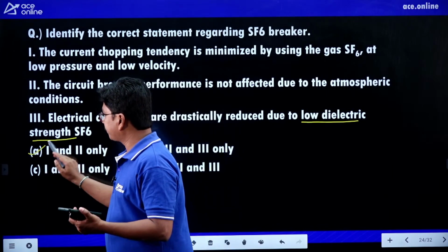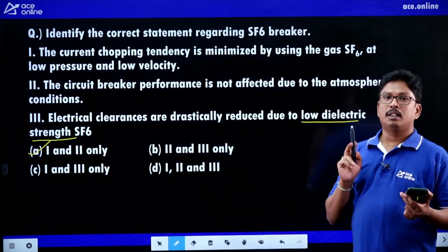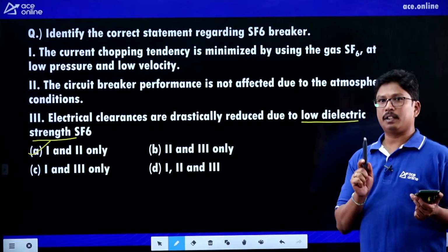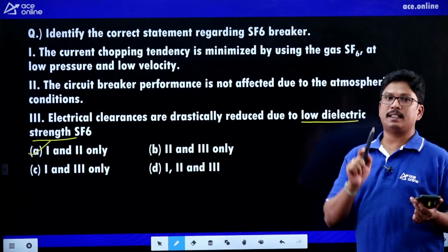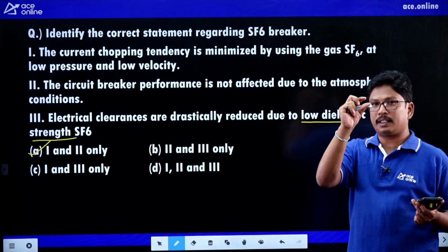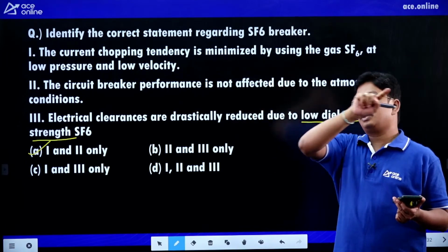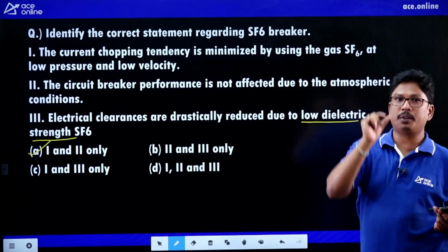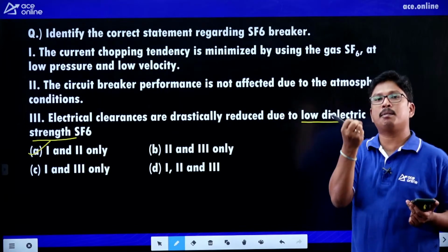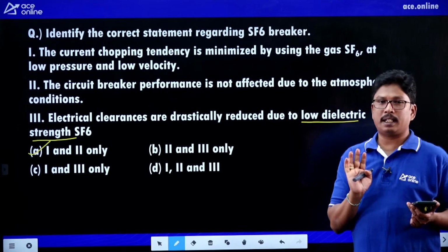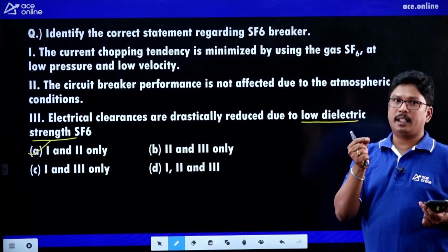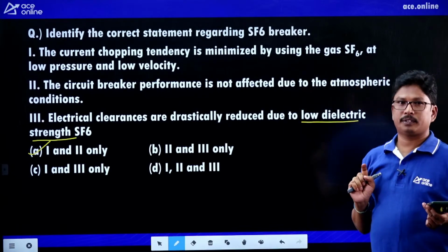Yes, Sai Kumar. Actually, the fuse element decides the fuse current rating. If the fuse conductor is somewhat thin compared to the line conductor, the line has more current capacity than the fuse. The fuse has somewhat less capability, so it can melt faster. So the fuse element decides the current rating, right? Very good.